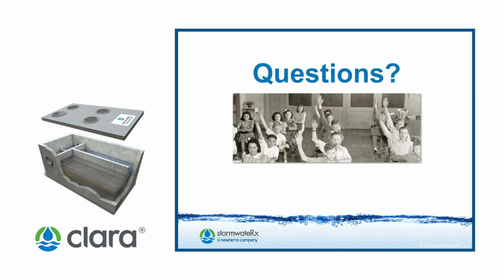Hi, Sharon. You had another question with regards to maintenance. You asked, how long do you need regular maintenance? I think that would be site specific. It would certainly be dependent upon the suspended solids entering into the Clara filter from that site. As with any BMP, it's hard to predict the length of time or the maintenance interval without actually installing it and running it.